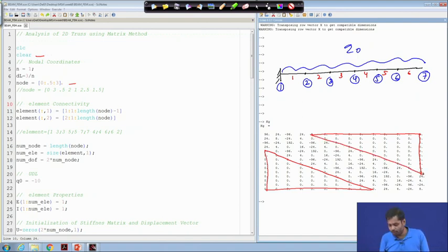So, the only non-zero elements in the stiffness matrix are the diagonal term and a few off-diagonal terms. The advantage of having a banded stiffness matrix is that when you actually try to solve it, at the end of the day we have to solve some system of linear equations, and the operations while solving these equations are much fewer.